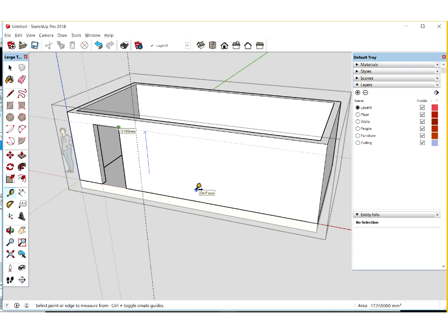Window head height and door head height are often the same on a building, not always, depends on the effect that you want. I just wanted a vertical height point somewhere there, either at sill height or head height, because we're not starting this one from the ground, so we needed some additional height reference point there. So from any height reference point, you could start from the bottom and do a 1200 sill or something like that as well. Use the rectangle tool, draw a window size to whatever size you want, type in some dimensions.